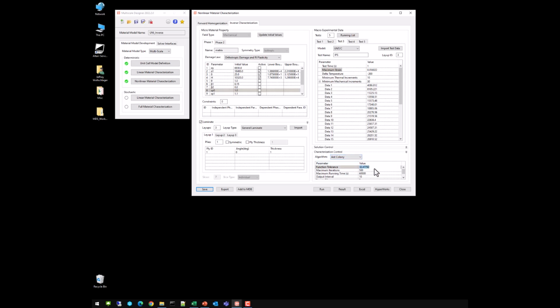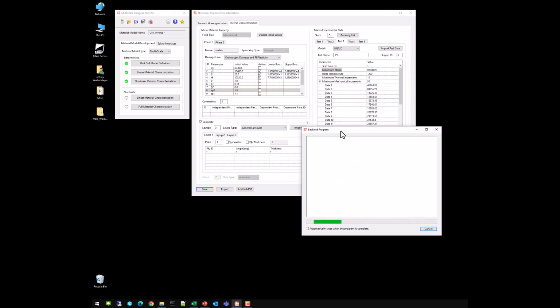And it's going to do that until it sees an error less than 32. The sum of the error at all 30 points has got to be less than 32, which is a pretty low number when we're talking about things in the 10,000s. And I'm just going to start with 50 iterations, so try 50 genetic spawns. You can change that number. I just don't want it to run forever. So let's go ahead and launch this optimization, and let's see what comes back.